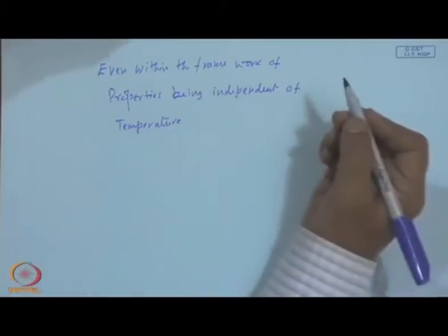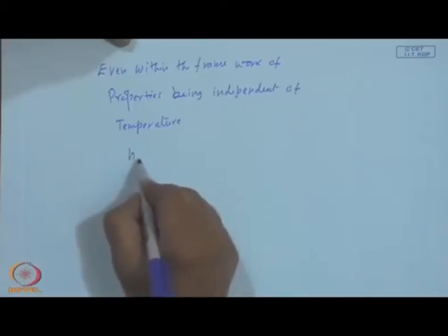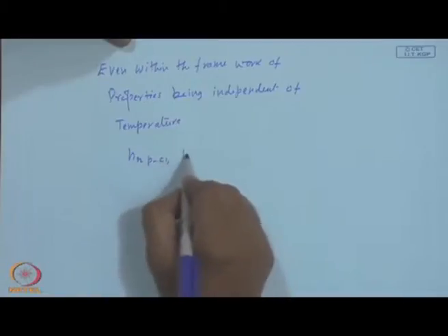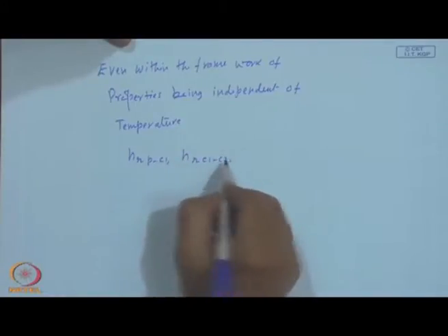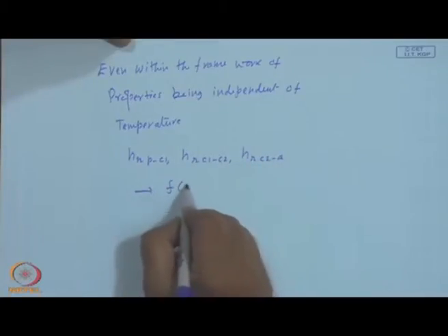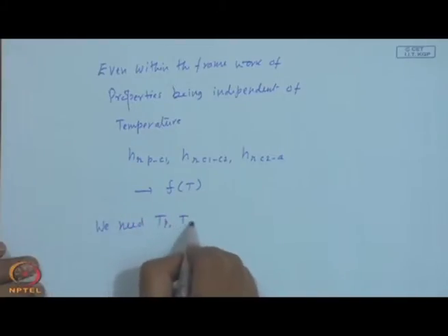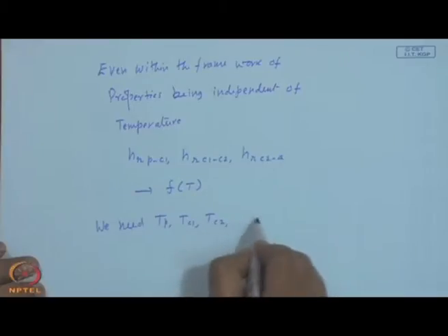that means the thermal conductivity does not change, heat transfer coefficients we have a method of estimating it, and the viscosity, density, they do not change with temperature. But even with all these assumptions, my HR P2 C1, HR C1 C2 and HR C2A, they are functions of T. In other words, we need Tp, Tc1, Tc2, Ta, and of course, T sky.